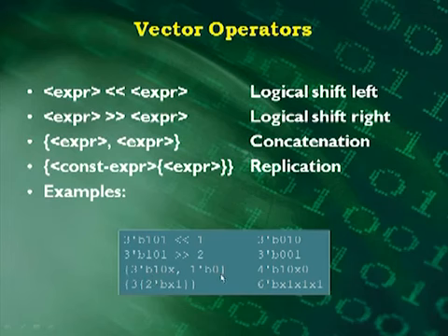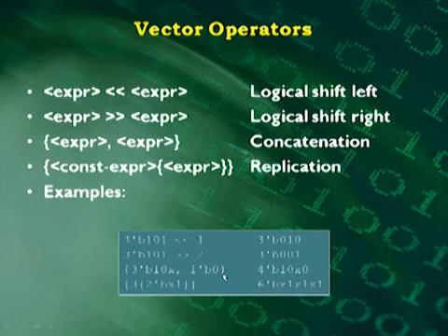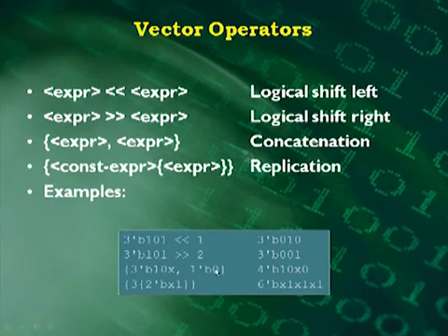Now, in this case, you use curly brackets in the Verilog code itself, right here at the beginning and at the end. And you have some items separated with a comma, like we show up here in the syntax. So these curly braces are part of the Verilog syntax in this case. And here we have 3 bits with a value and a single bit with a value. And by concatenating them in this manner, you'll get 4 bits. And hopefully that's fairly obvious.